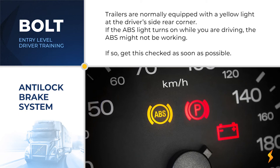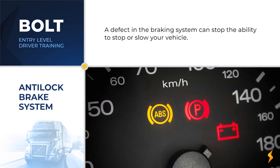If the light stays on or suddenly turns on while you are driving, the ABS may not be working. Though you still have properly working brakes, the anti-lock function may not be working. Get this checked out as soon as possible. A defect in the braking system can interfere with a vehicle's ability to slow and/or stop your vehicle.